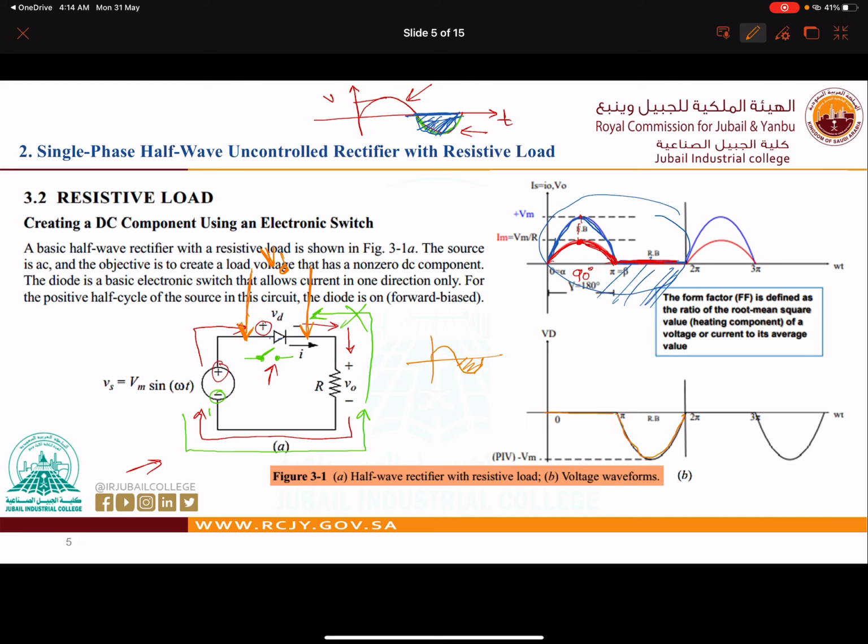Okay, so once the diode is reverse bias, there is an open circuit. Remember, there is an open circuit here. Then we have a potential difference between those 2 points. Then we will have voltage. Of course, it will be the voltage of the supply. So this is the remaining of the voltage of the supply. This is for V diode, voltage of the diode.